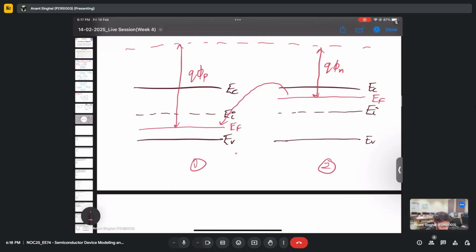And you need to just focus on how the electron moves and how the conduction band edge will move with respect to the Fermi level. So this is the conduction band edge. To move this electron from here to here, this whole thing will somehow come down. I'll let you know the exact band diagram; this is just a basic idea. This is what we call band bending. So there will be some bending of the bands, and that is how we make the band diagrams.